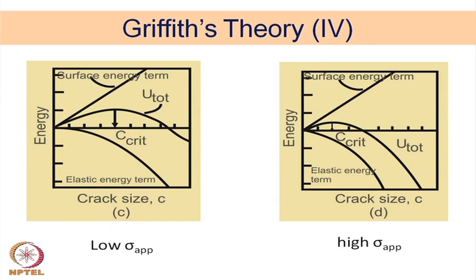Okay. So, that does not grow, because here the energy increases when the size decreases, whereas on this side the energy decreases when the size increases. So, this part will automatically increase on its own, this part would automatically decrease, whether it is an embryo, a critical nuclei or a crack. So, a very analogous situation happens like that of the nucleation and growth theory of phase transformation.